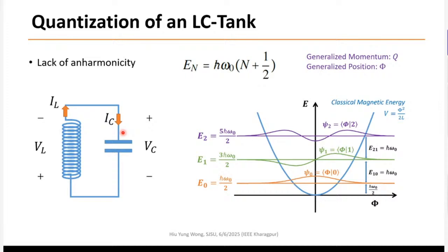When it is at a very low temperature, you can imagine you can only have 1 unit of energy. And by the way, this is a resonance circuit. Only one frequency can exist, the resonance frequency. That frequency, which is h bar omega, corresponds to a packet of energy, or you can call it a photon. Now, you may get confused. What? We are talking about a microwave circuit, and now you're talking about light? No. A photon, in general, is just any electromagnetic wave. What we can see, a short wavelength, 500 nanometers, for example, they are not microwave, but they are photons one by one. But microwave is also an electromagnetic wave. So that's why very often we talk about photons in the quantized circuit.